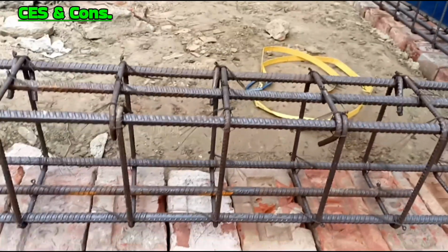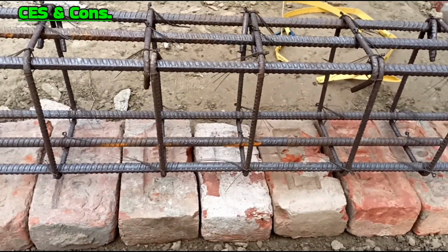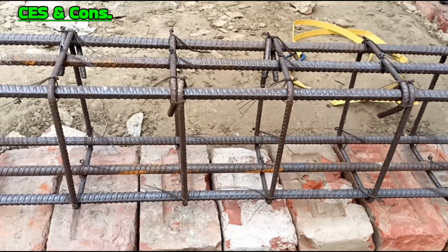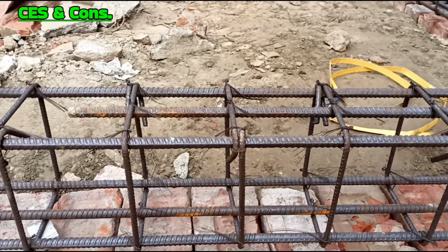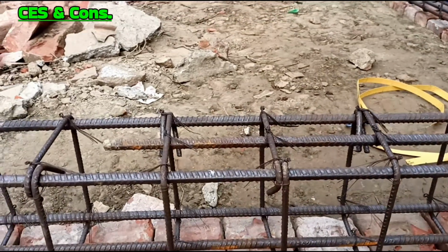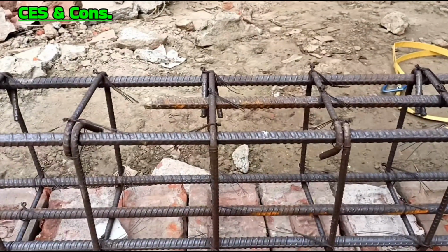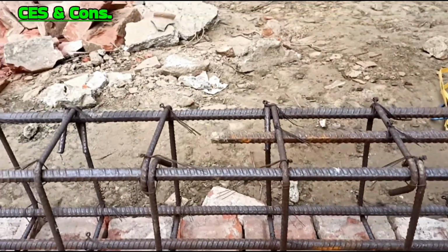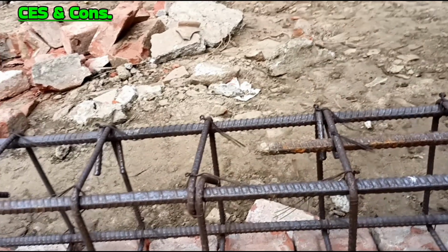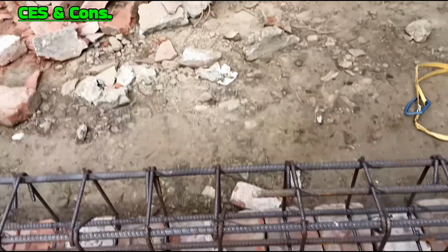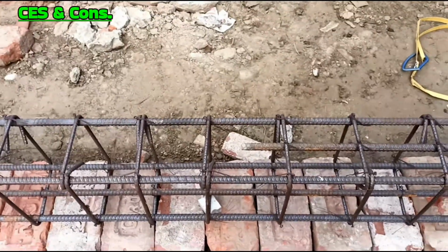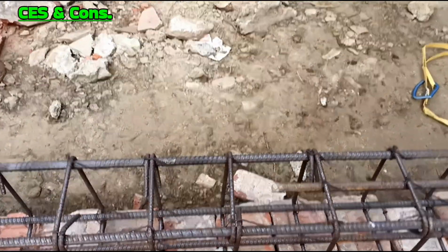are guided there. Stirrups resist shear force and prevent diagonal cracks caused by these forces. They are particularly critical in areas near the support of a beam where shear stress is maximum. Stirrups also improve the ductility of the beam and ensure that the concrete in the core remains confined, which enhances the beam's capacity to absorb energy and deform without failure.